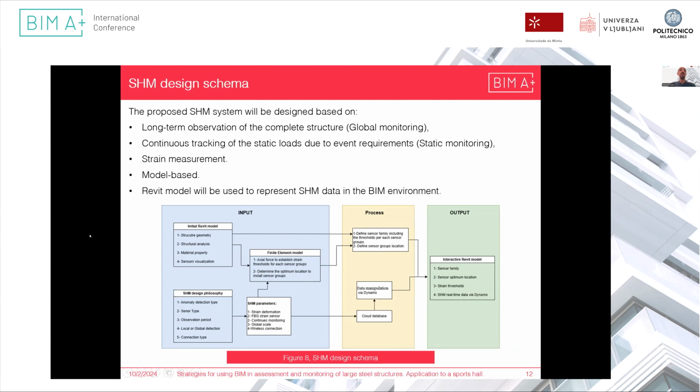And of course, we will generate a finite element model for verification and to find the sweet spot for the load that we will apply. And of course, we will develop a Revit model that will later be used as a structural health monitoring warning system. We have here the initial Revit model. Of course, it contains structural geometry, structural analysis, model properties, and sensor virtualization.